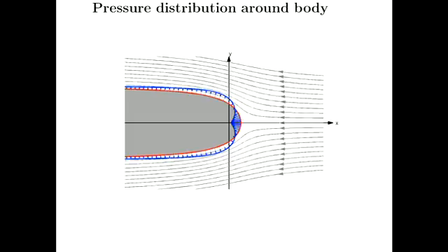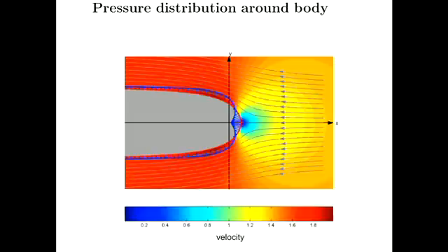And if I include color contours here of the magnitude of velocity, you get a sense of what's going on. You know how to read one of these pseudo-color plots, right? The blue color indicates low velocity, and the red color indicates high velocity. Right on the nose of that half-Rankine body we've got low velocity.